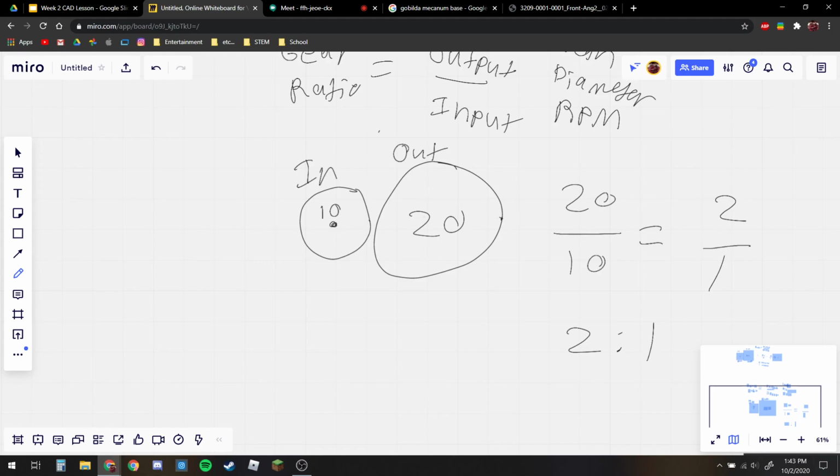Your motor is doing less work, which means this will generate torque, which makes you stronger. You're essentially making the motor stronger than it actually is. However, you're sacrificing speed. You can't have both. You're either weak and fast or slow and strong.